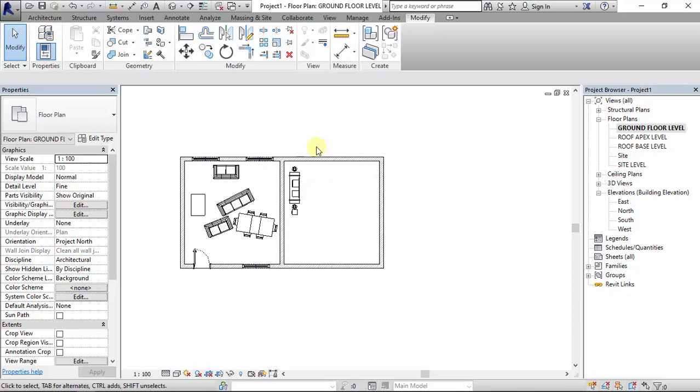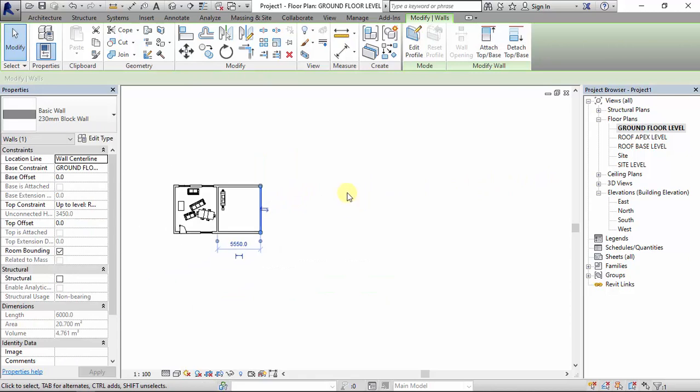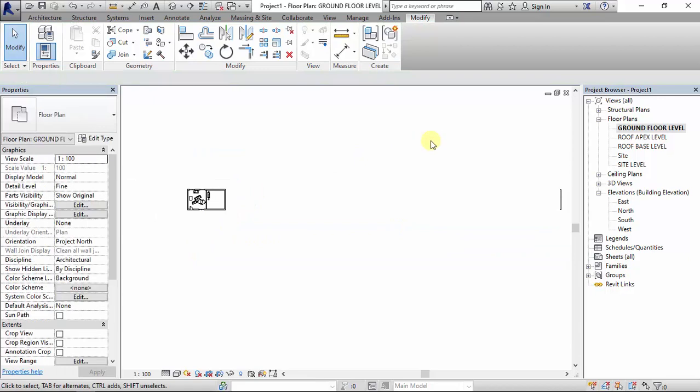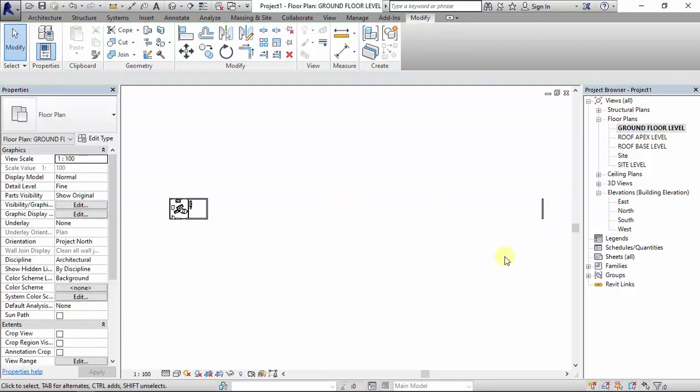For example, if I want to move this wall, let's say 100 meters now, rather than doing 100 because I'm in millimeters, rather than doing 100 then typing in 0000, I can just write 100 m, then it moves it, copies it by 100 meters. So rather than you bothering your head about the conversion in your head, you can just hit it with the units, then it takes it.